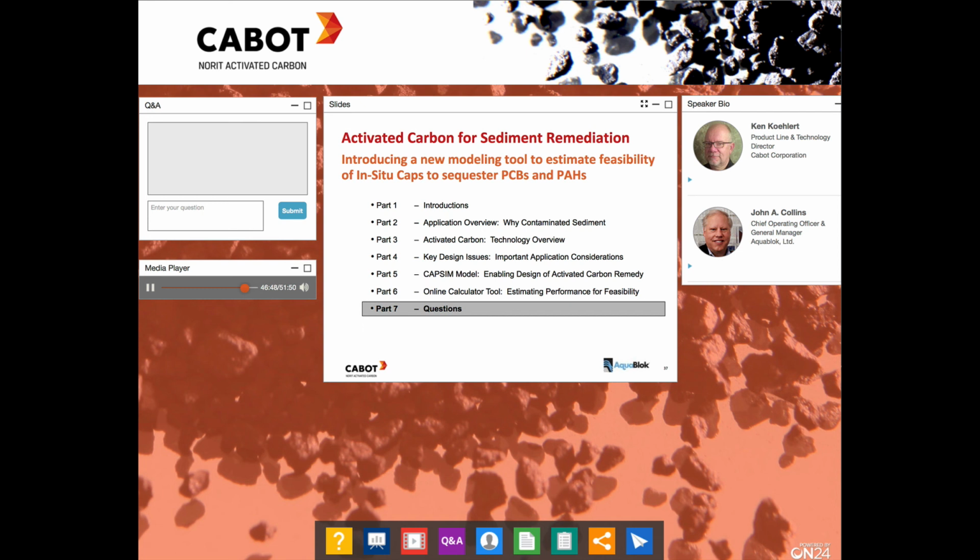You can look at the nearshore groundwater flux rates and assume. Sometimes people assume that the water that's moving through the ground immediately adjacent to a water body is what's coming up through the sediments in the water body as well. So there are direct measurement capabilities there. Again, I'm not an expert on that, but it's definitely an important question from the standpoint that you need to understand what the velocity of that flow rate is in the sediment regime.